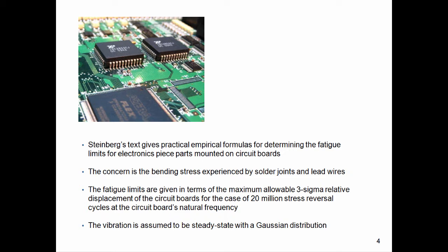Another situation that we run into is that the vibration is not necessarily going to be steady state. We may have some non-stationary vibration, where the level rises and falls with time, or the levels even shift frequencies with time, or at certain durations the avionics box might have to withstand sine vibration, and then later on random vibration, or a mixture of both, or any combination thereof.